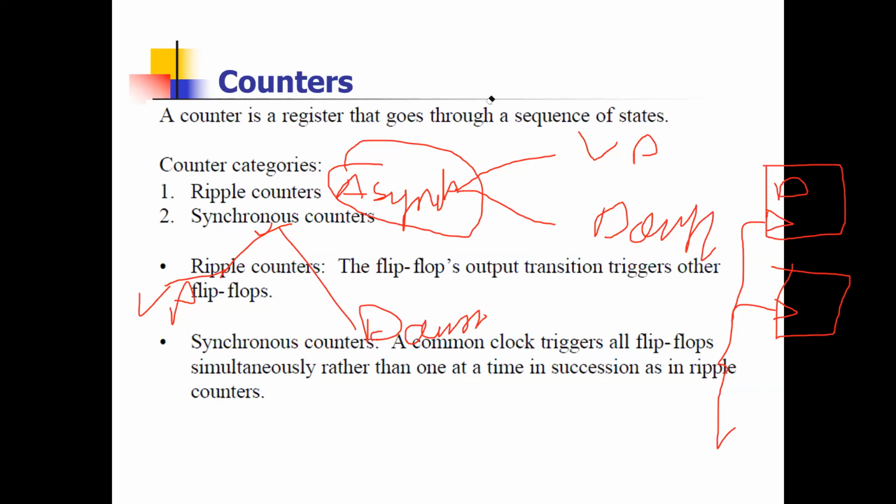We gave the same clock. That means the designing which we studied already in chapter 5 is the designing of synchronous counters also. Synchronous counter means synchronous sequential circuit because it has flip-flops. So the steps which I taught you in chapter 5, we will follow the same steps for the designing of synchronous counters.